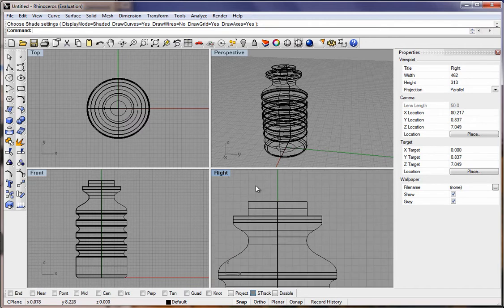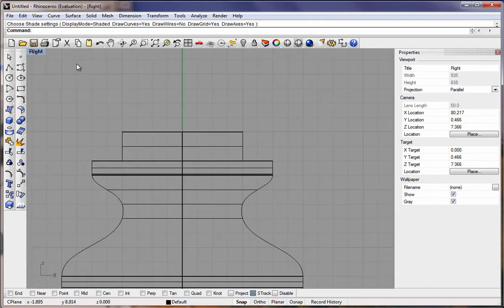So on this right view, zoom up to that. Actually, we could just maximize it. And we're going to take the curve and the plate points, snap to this point here. Actually, I'm going to hit escape for a second. Let's click on that again. And make sure you start tangency. Click on that point, drag it up. And we'll drag it across here. Then end tangent. At the middle, click and drag it straight across. So that's the front. And now the back is going to have a little notch on it.